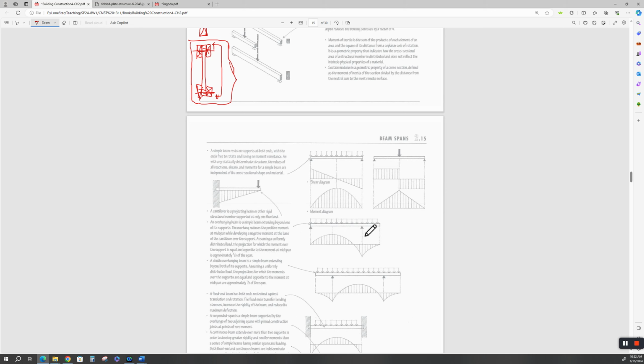If you overhang, you put a cantilevered overhang on a beam, then the beam will carry less moment in here. The moment diagram is smaller. If it's a simple span like that, or if it's a cantilever, you've reduced the moment by sticking this cantilevered section out.